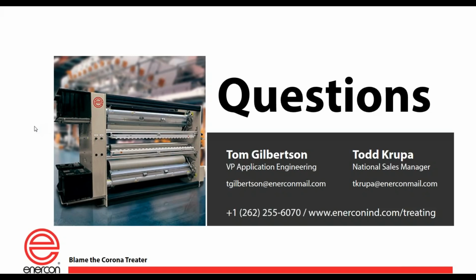Well, that actually is very simple. So I want you guys to think about this. What's a corona treater? What is corona? What is it? Ionized air. Thank you. Corona's ionized air, and if you look at what foam is, what's foam? It's basically all air. Whether it's closed cell or open cell, you got a lot of air in there. So of course, if it's open cell foam and it's only like a 2 or 4 pound foam, and you turn a corona treater on, you get this discharge, and it's ionizing the air that's in the foam.